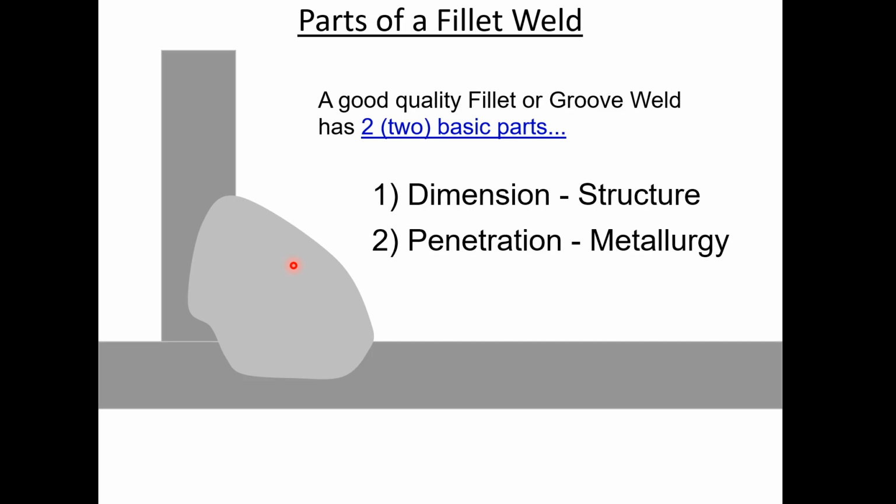And certain materials will start to crack if they're not welded in a certain method. So we do a lot of work out in front to make sure that you have the correct metallurgy, like the wire that we've determined. They call this procedure when we're developing procedure: the correct metallurgy, the correct amount of heat input, that is the parameters of the weld to give us penetration. And then, of course, we teach you technique, how to do it.